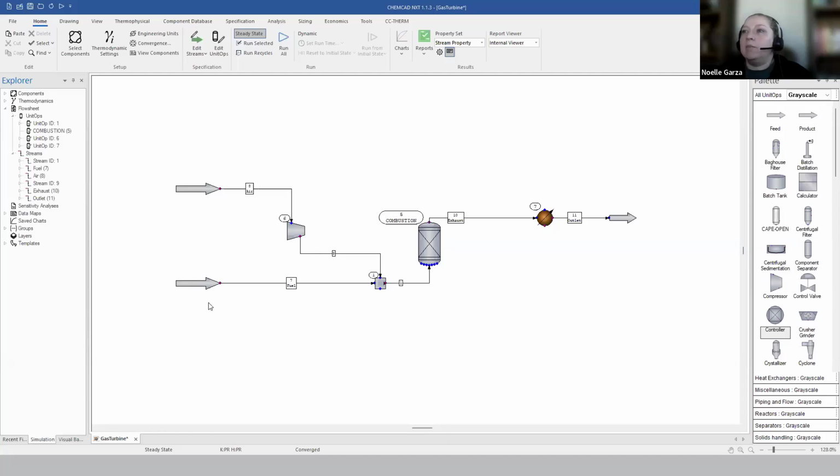But in the interest of time, this is a pre-built example. In this case, we're trying to build a flow sheet, but we're in the early stages of design and we have a lot of unknowns and uncertainty around defining the variables. If we're uncertain about these variables and our flow sheet design, we're going to use sensitivity analysis.